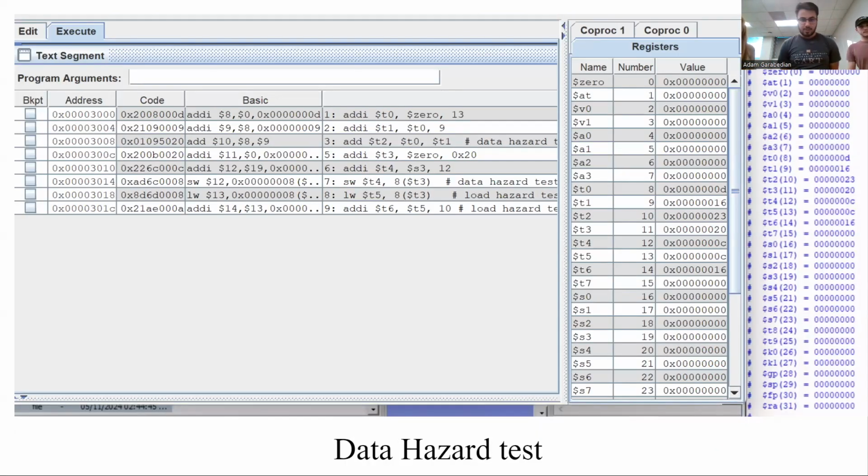To show the data hazards, like I mentioned earlier, there's going to be some conflict in actually reading data from places. For example, the first 2 add immediate instructions, one of them writes to 8, but the second add instruction will then use 8 in the next one. So it has to forward or stall. In this case, I think it will just forward it. But you can see the expected results are on the center right from the MIPS from Mars, and on the right is from our Verilog script. You can see that the registers align.